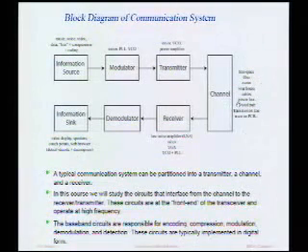There's also some channels that you might not really think about as channels. So for instance, just sending information from, let's say, your laptop to a hard drive using a USB cable. Now we don't really think of that as a channel because it's just a wire, but in fact, if you really want to get the most throughput through that link, you do have to analyze it as a communication system. In fact, just putting traces on a PC board can be analyzed as a channel. If you really want to send lots of data, let's say a server communicating with high-speed memory on a PCB, you have to analyze the communication properties of that channel.